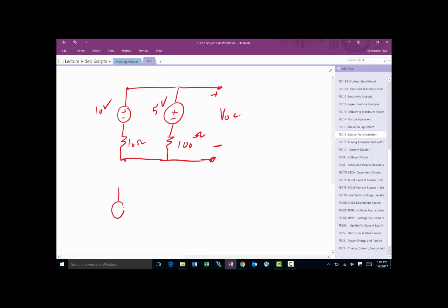So I can really rewrite this one as a current going up and a resistor. So I'm going from a Thevenin equivalent to a Norton equivalent. And therefore, I here has to be 10 volts divided by 10, because I short circuit is V open circuit divided by R Thevenin. So it's 1 amp. And of course, the resistor is just going to stay the same because that's R Thevenin for that. And I can take this circuit here and do the same thing to it.